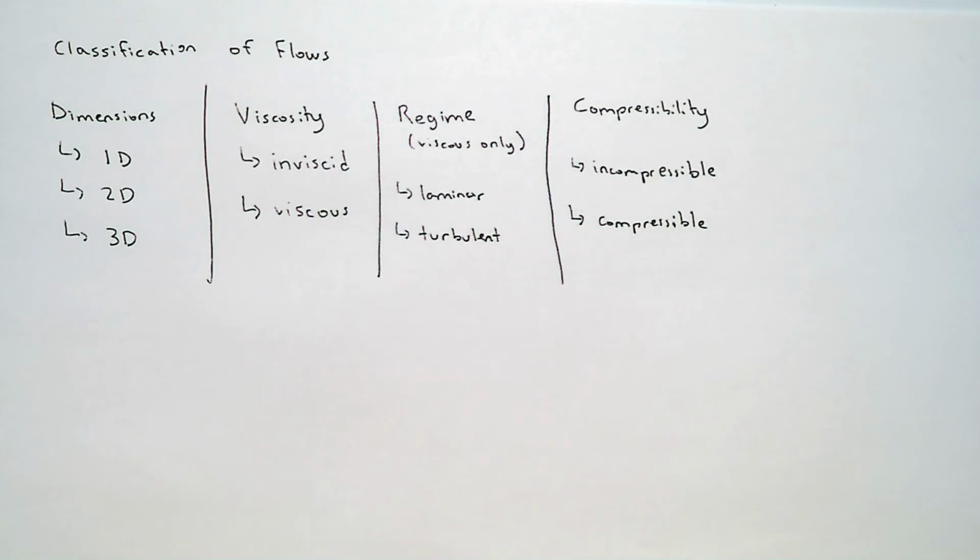If our fluid is compressible, then any change in pressure is actually going to deform my fluid, and therefore my properties such as density and viscosity will change. If my fluid is incompressible, then any change in pressure will not deform my fluid, and therefore I have fewer equations or parameters to worry about. Now, as an engineering approach, we can assume that most fluids are incompressible, liquids are incompressible. But we cannot do the same for gases.